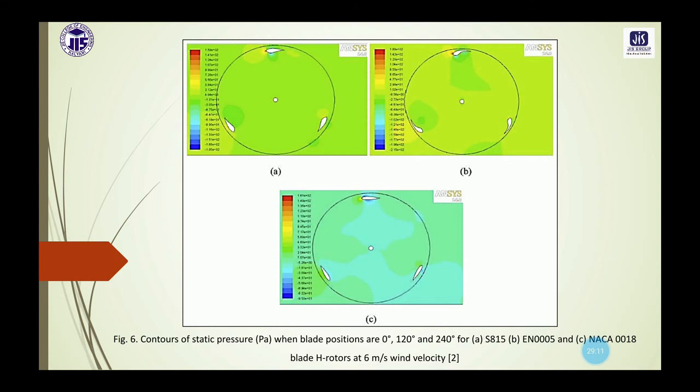So various such turbulence models are there, and we need to choose wisely which turbulence model is suitable for our analysis. After choosing the turbulence model, we can perform the simulation in two different ways, one for steady state and another for unsteady or the transient state. And after that we need to provide the iteration steps. In the software we will perform the number of iterations, and when the iteration gets converged,